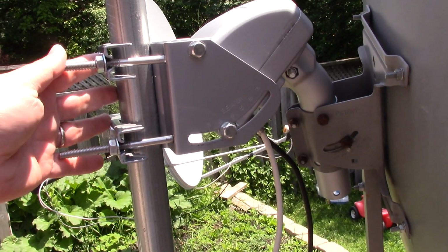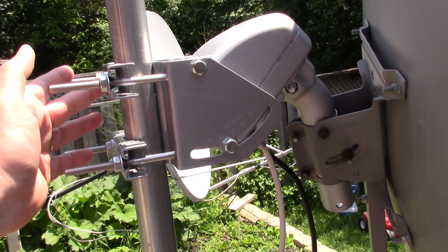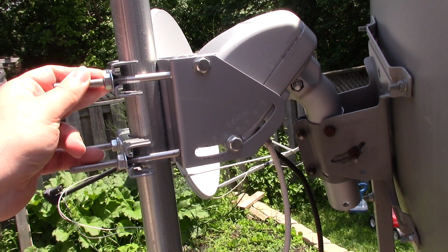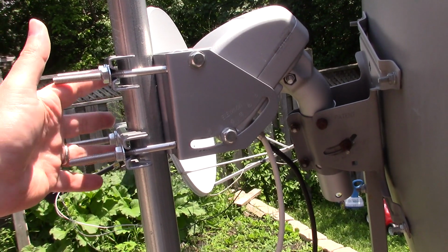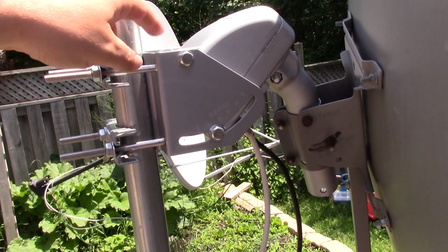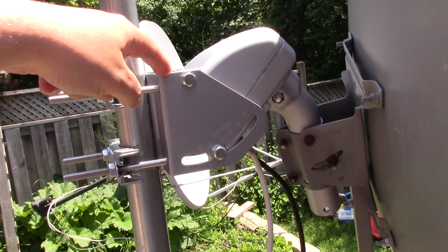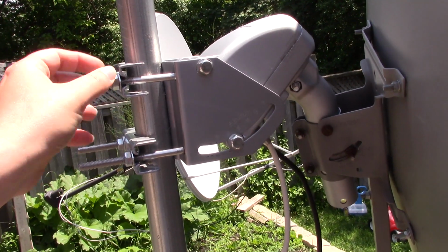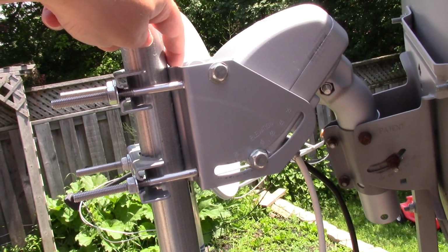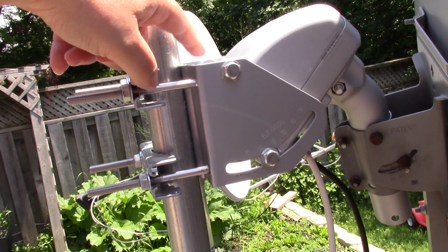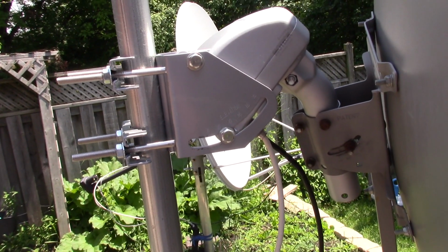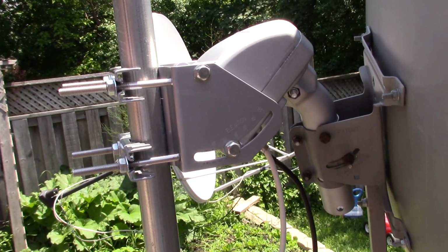The interesting thing is, there's other satellites that had transponders, but the ones that I had scanned in, even though it was maybe like 9 degrees off of where my true south was, I was still able to lock it and then able to lock onto the geostationary arc. So you just want to tighten this. Now, one thing that will be a factor is when you do loosen this, this will be off by a little bit. But once you tighten it up, you should be able to adjust that, and you should be able to get the full arc of your geostationary satellites.